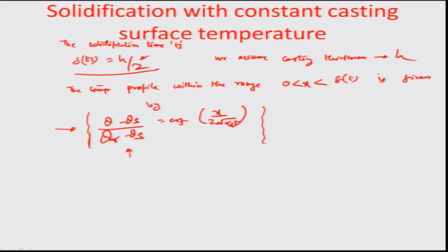Okay. So, in this case I will just mention that theta infinity is an integration constant, and we will not bother about it because ultimately we need not use this value for our calculations. Okay. So, this is a constant of integration. If you remember the whole process of the solution, there were many integrals which were formulated in order to estimate the real value of theta, and alpha s basically is the thermal diffusivity of the mold, which was actually also recorded as the thermal conductivity of the mold per unit density times specific heat capacity of the mold.